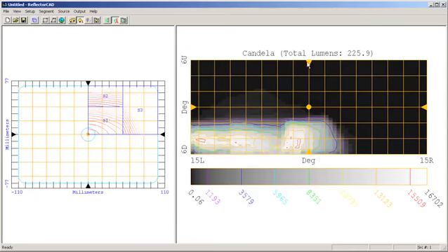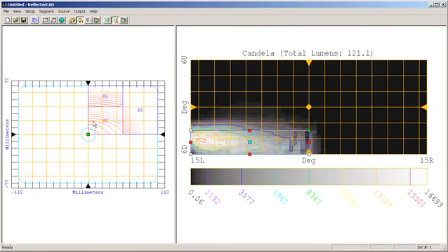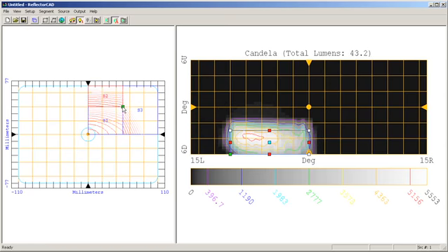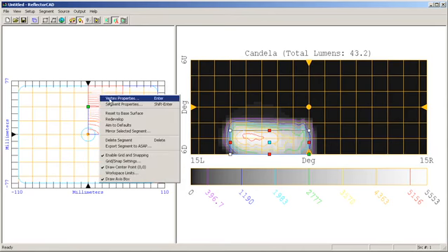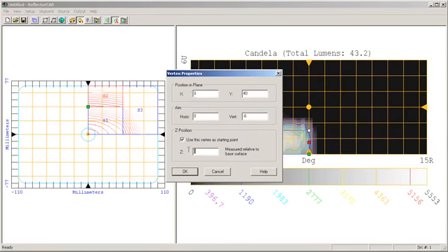I can also look at that information numerically inside of ReflectorCAD. By highlighting a segment, such as my center segment here, then with the Shift and mouse keys, I can determine how far in front of or behind a particular segment is with respect to another segment. Green is good, red is not so good. Now what I can do is come into each one of these individual segments, go to their vertex properties, and actually shift them with respect to one another.